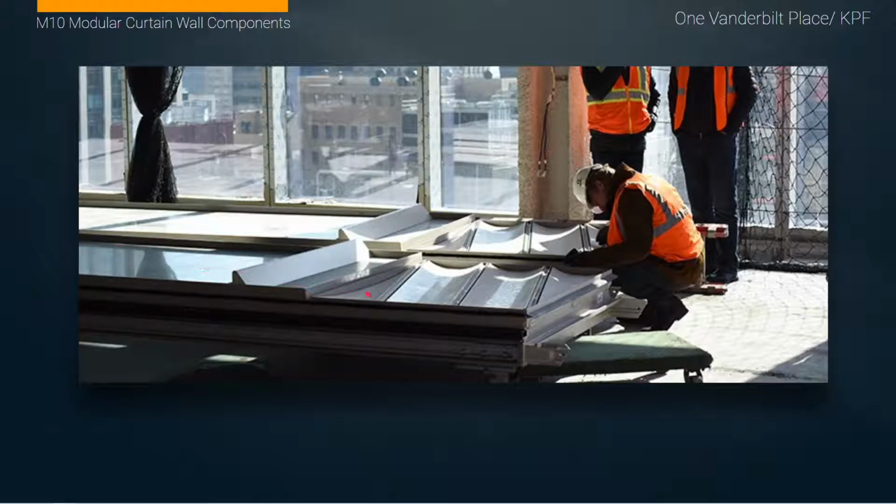So here we have our glass, our curved terracotta tile system, this kind of a trim transition piece. And notable, and something that is really beyond the scope of an introductory course in computer visualization, but interesting nonetheless, is the clip system. So here we have these aluminum extrusions that form the module, and then bolted to it we have these clips. These clips are what will be the attachment both from one unit to the next and then tying back to attach to the building.